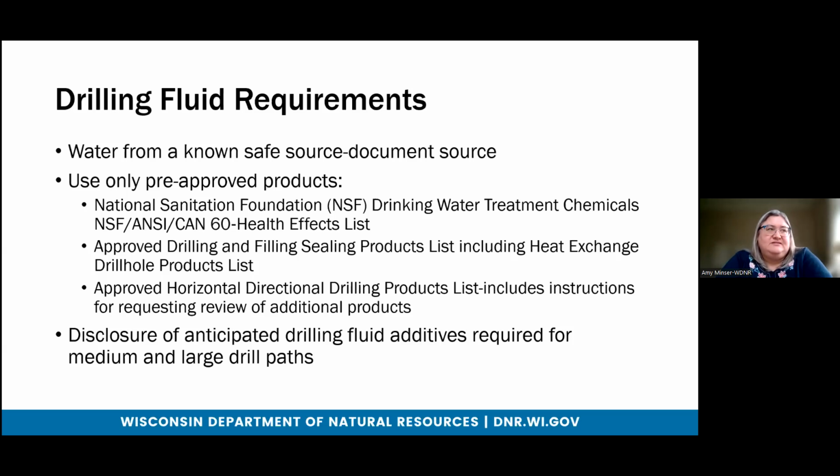The other piece is to only use pre-approved products. By code, anything that's on the NSF 60 health effects list is presumed to be pre-approved. There's also an approved drilling and filling sealing products list, including heat exchange drill hole products list, on the website under well drilling.